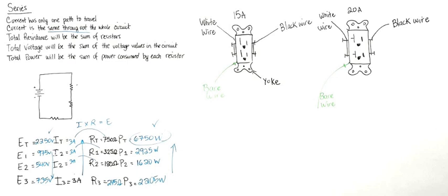Now most of us, for me for example, 90% of the time we never worked with power. What we did is identify the circuit, turn it off at the panel, lock it, tag it, and make sure nobody turned on the power while I or somebody else was working on it. We would fix or troubleshoot whatever we needed to do, and then we would turn it back on, right?